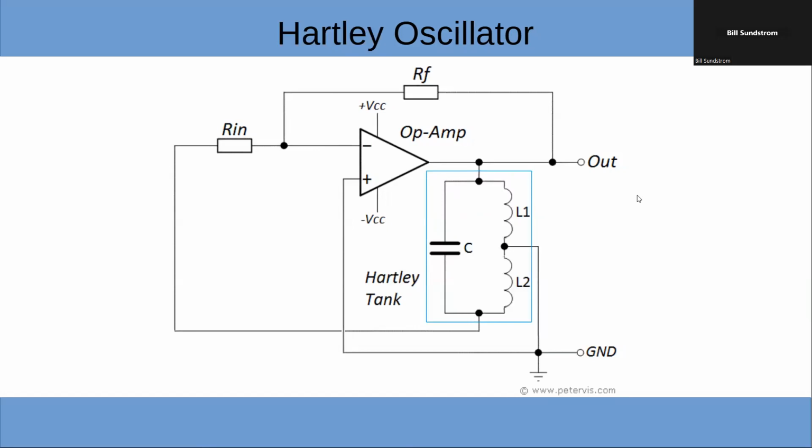The other one that you'll hear about is called a Hartley, again after some guy named Hartley. And you notice that we've swapped the components. The resonant circuit is now a voltage divider or a tapped inductor and a capacitor. So one way I remember, Colpitts has the capacitive divider. So C for capacitive divider for Colpitts. So obviously then the Hartley is the other one.